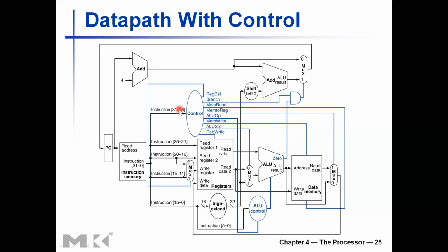So is it necessary to have separate controls for memread and memwrite? Good question. It appears in this particular case you can do with only one signal, right? If the signal is 0, this. If the signal is not 0, that. Yeah, so it appears like that.